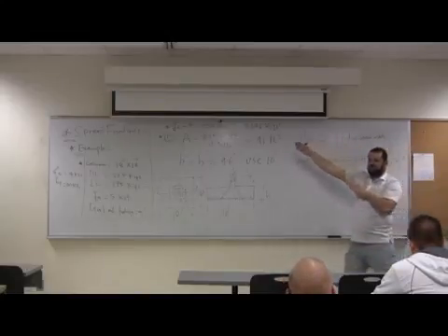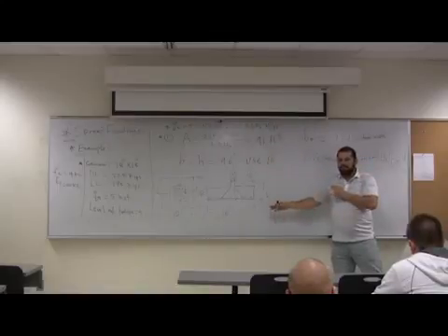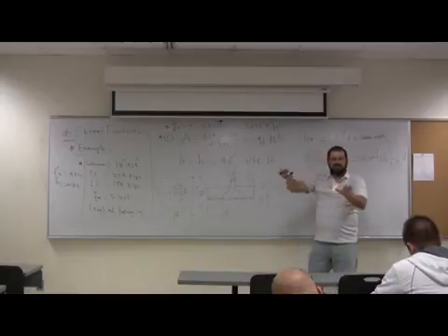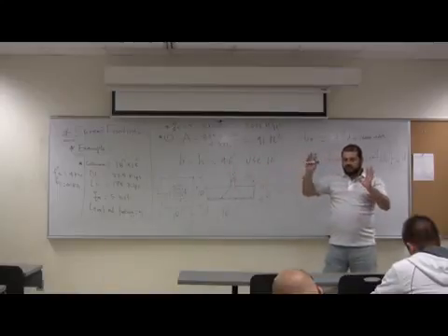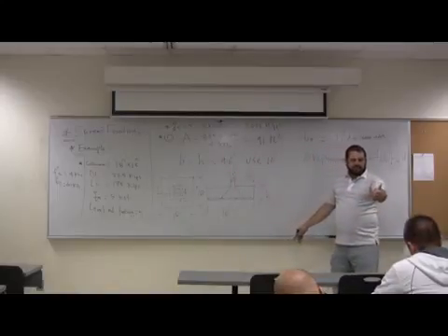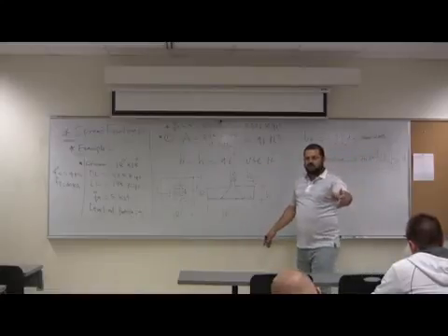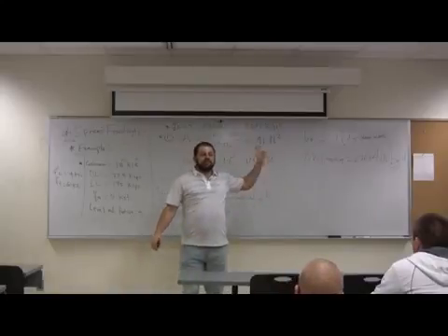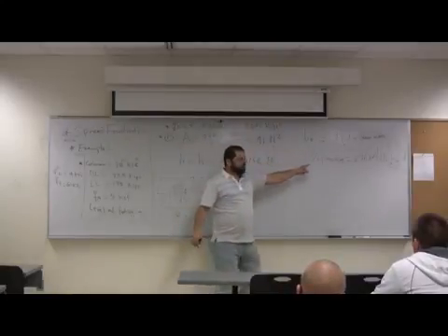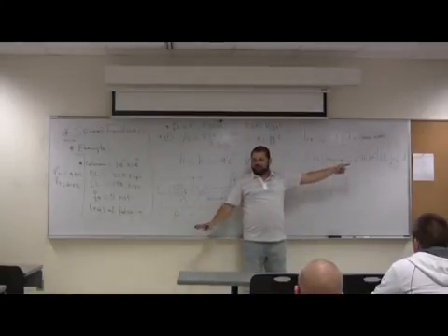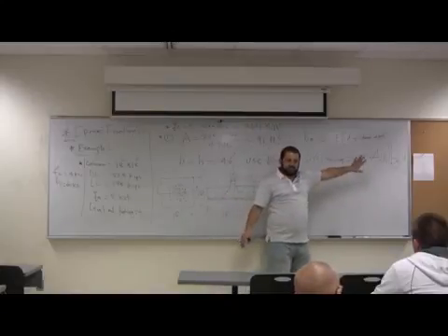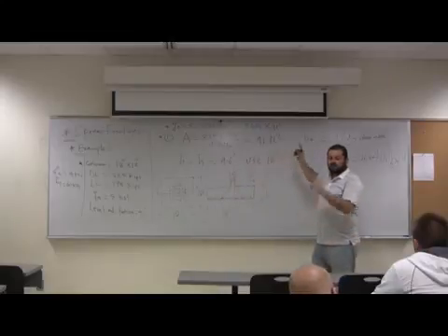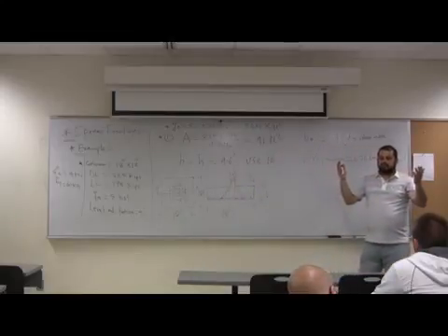Again, now we have the area. What do we need to design? D. Once we have D, we can calculate the moment and find the steel. The structural design is so easy. The only thing we need to find is D. In the FE exam questions, the one that I read, they ask you to check how much the punching shear strength is. Basically, they're asking you to calculate this one. They give you D and everything. You just need to find B naught and do this multiplication. So in our case here, the only item we need is D.